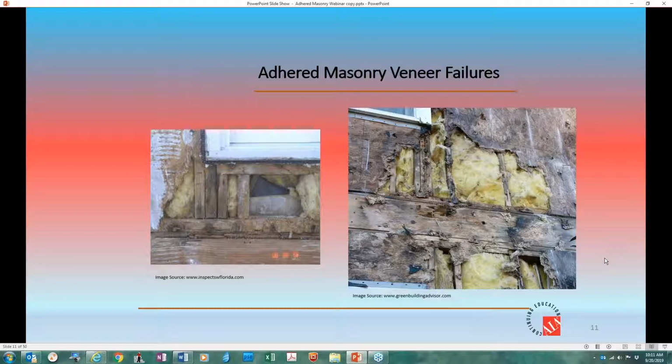That was extreme, but the principles are the same. This occurs when an entangled or a high loft non-woven drainage mesh is used. They're made of polyester or polypropylene. Those are the two mesh types available on the market. They both perform very, very well. Neither one is preferred over the other. And they're basically placed between the WRB and the scratch coat.